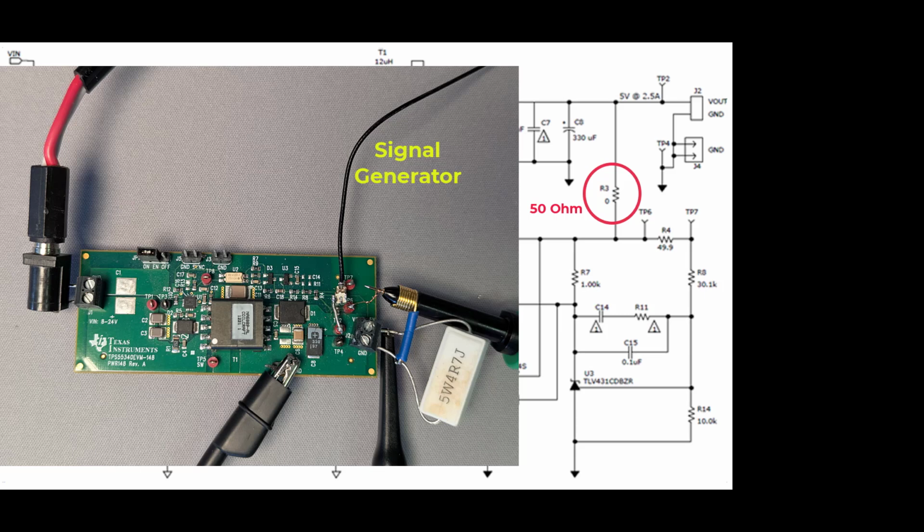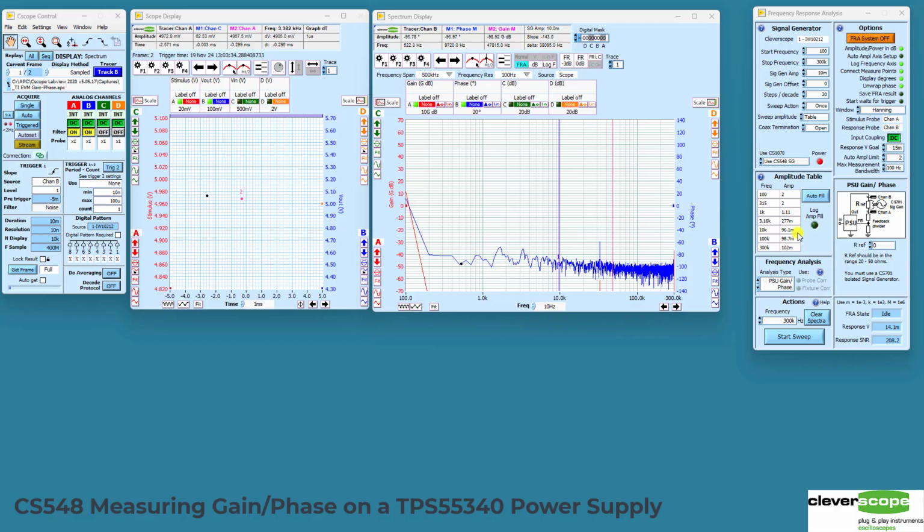Connect the isolated signal generator across R3, the 50 ohm feedback resistor. Connect channel A, the stimulus, from 0 volts to TP6, the feedback resistor divider point. Connect channel B, the response, from 0 volts to V out, the output. Open and display the windows as you see here.